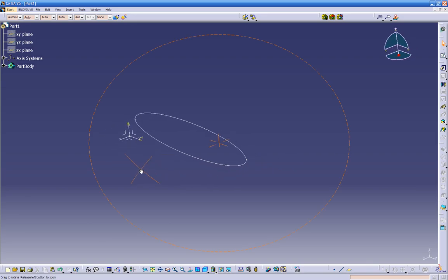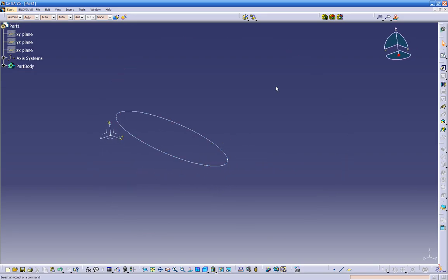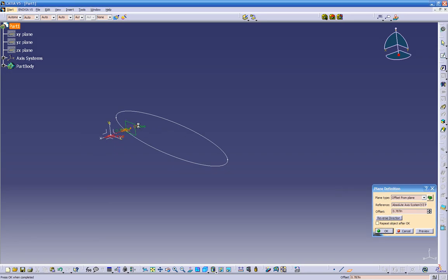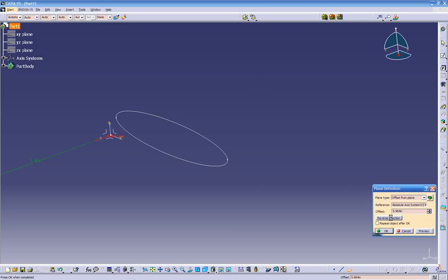So that's an ellipse right there. So let's offset this plane over so we can create another shape over here, so we can create our multi-solid. You can tell by the icon, you know, it's got multi-sections curves that we can apply. So let's go to the plane and let's go offset. We can put the reverse direction, and if you click on the arrow, you can move it up and down. Okay, so go reverse direction, and it's the direction you prefer. Let's make it 6 inches.